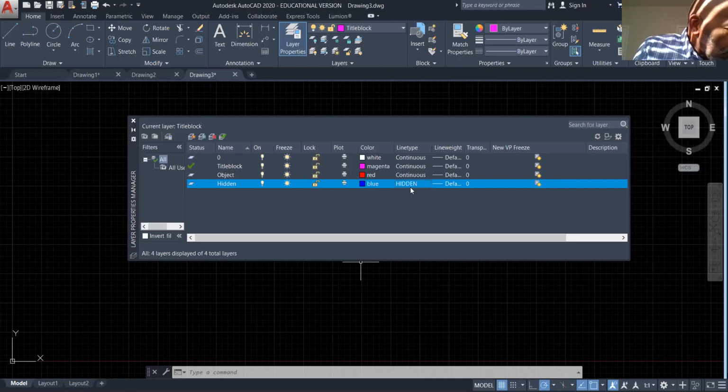Don't worry about the depth points layer. Depth points is the default AutoCAD non-plottable layer, but we're not going to create that. We're going to create our own non-plottable layer named non-plot. So just go ahead and do that. When you do that, then I'm going to come back and you want to save this drawing. That's going to be the last thing that we're going to do for this session. So I'm going to let you go ahead and create the layers.